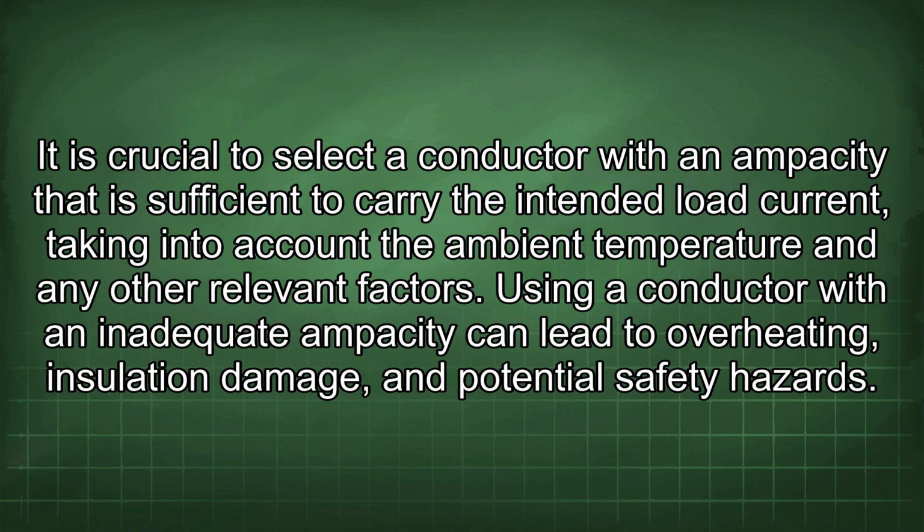It is crucial to select a conductor with an ampacity that is sufficient to carry the intended load current, taking into account the ambient temperature and any other relevant factors. Using a conductor with an inadequate ampacity can lead to overheating, insulation damage, and potential safety hazards.